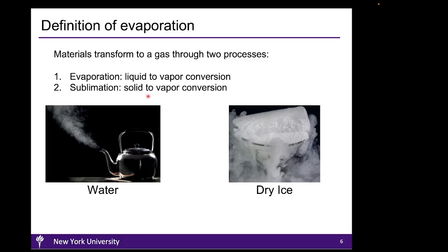Evaporation involves the phase transformation of a material from liquid to gas. Therefore, the evaporation of solids requires them to melt first, followed by their conversion to vapor. A prime example of this process in nature involves the transformation of water to vapor upon boiling. Note that vapor can also be generated directly from solids. This process is known as sublimation. However, sublimation is not utilized in microfabrication for depositing thin films.